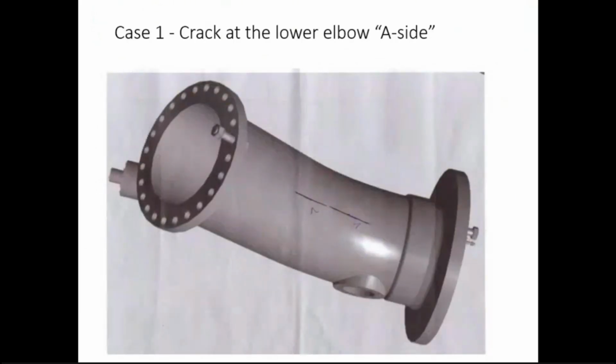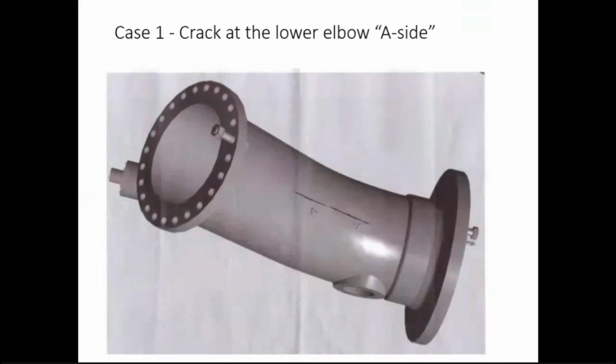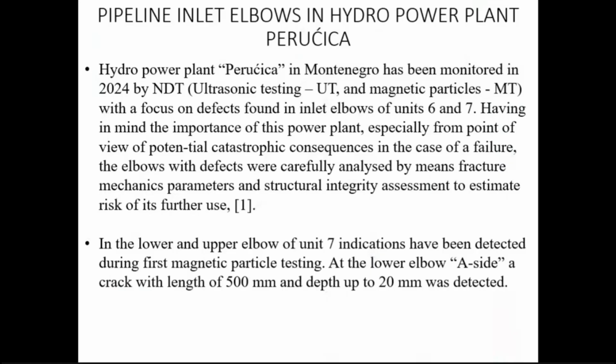In the case of the elbow, a number of defects were detected. As the most critical one, you can see this one, 500 millimeters long and 20 millimeters deep.